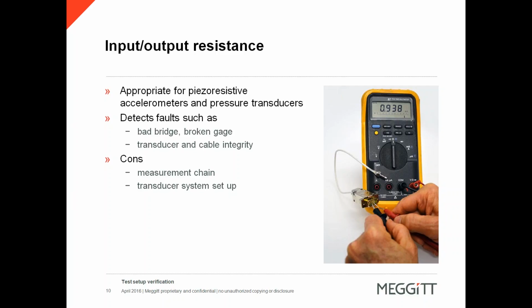Do you agree, Massimo? Absolutely, David. This is a good test method and I recommend it often to test lab professionals. We do need to remember, it does not check the integrity of the signal conditioning, the data system setup, or any applied low-pass or high-pass filtering option. Although labor-intensive, this is something that should be performed at any piezo-resistive device before a critical test.